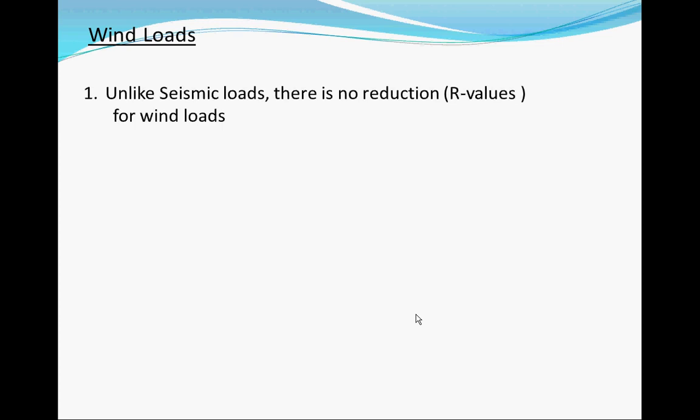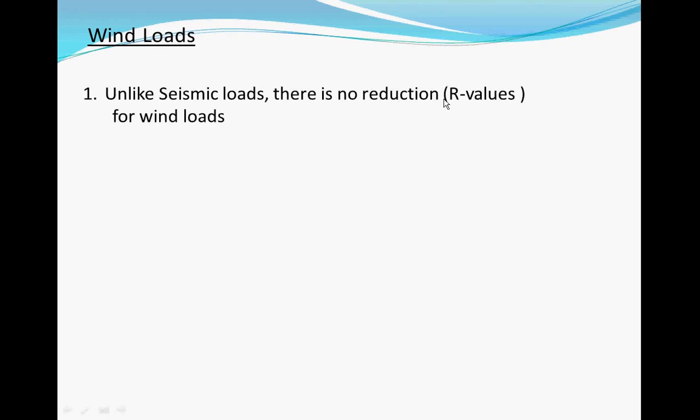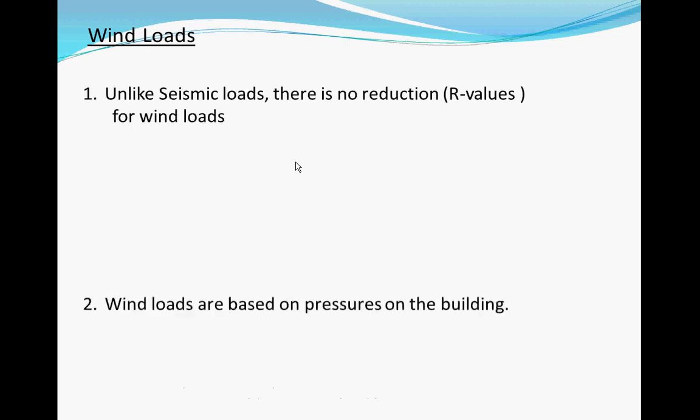Unlike seismic loads, like I told you before, there is no reduction value or R value for wind loads. So whatever wind load, whatever pressure you think is going to happen, you're designing for that force. It varies depending on the height and location, and I'll cover that quickly a little bit later. But we don't reduce the wind load per se for your design.